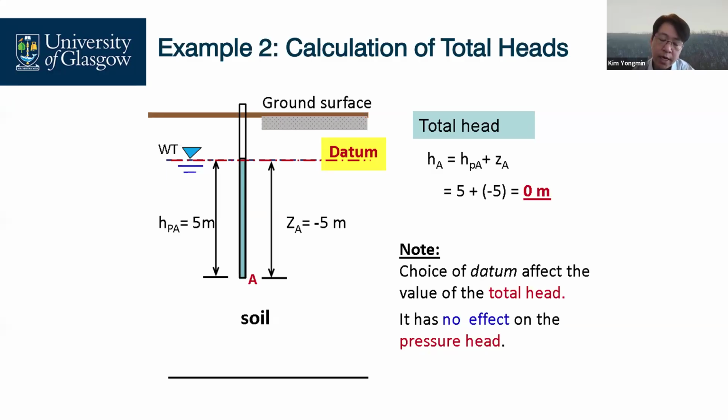Of course, we can install certain pressure sensors at a certain point, then you can work it out. For example, if the sensor tells you about 30 kilopascals, it means your water height would be 3 meters, because 30 equals 9.81 times your water depth, roughly 3 meters.